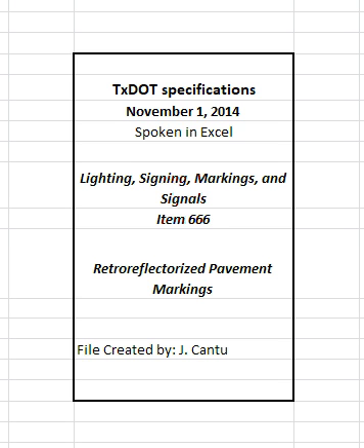4.5.1 Mobile retroreflectometer measurements. Provide mobile measurement averages for every 0.1 miles unless otherwise specified or approved. Take measurements on each section of roadway for each series of markings, i.e., edge line, center skip line, each line of a double line, etc., and for each direction of traffic flow. Measure each line in both directions for center lines on two-way roadways, i.e., measure both double solid lines in both directions and measure all center skip lines in both directions.